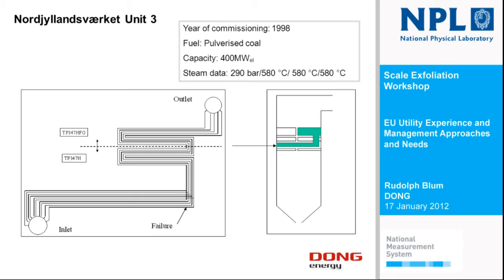Everything in the boiler. The boiler was in full operation, except the feed water pumps. And they were still running. And as everything was shut down, nobody could see it. But the man in the cellar, he recognized the problem, and he took the main stop of the feed water pump just before the water was coming to the outlet of the boiler. That was a real thermal shocking event. And it wasn't good, of course.